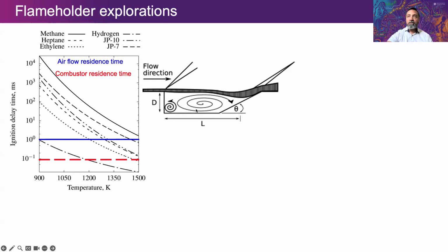The fuel gets entrained in here. There is a primary vortex and a small secondary vortex. These things are mixing and churning and spinning air and fuel together. There is a boundary layer which becomes a shear layer on top of this. Through that shear layer, we're transporting some of the mixed fuel air into a region where you have high enough